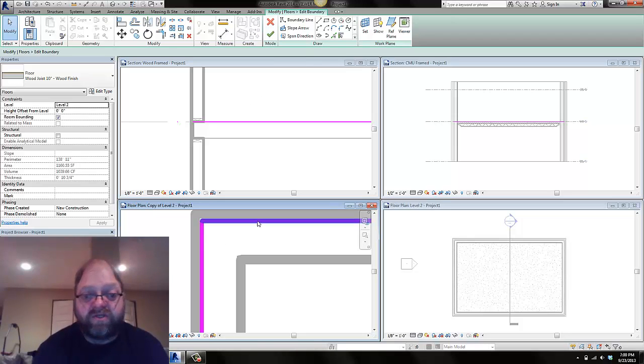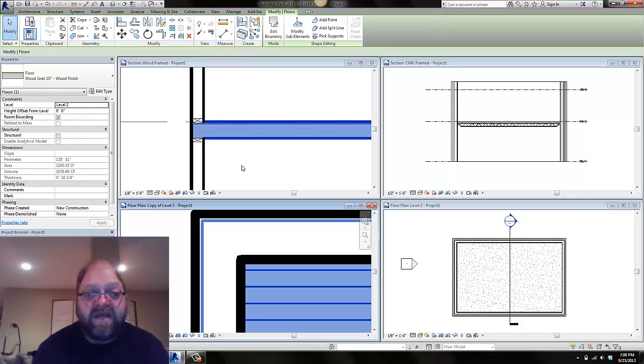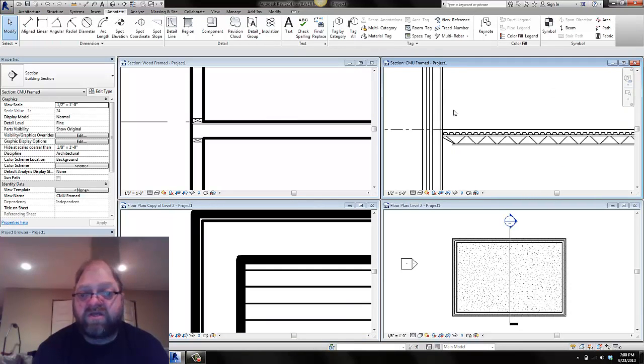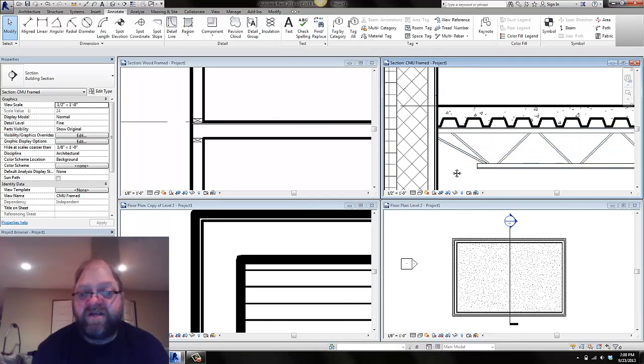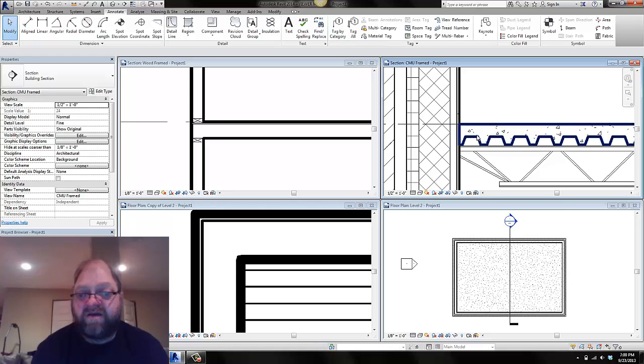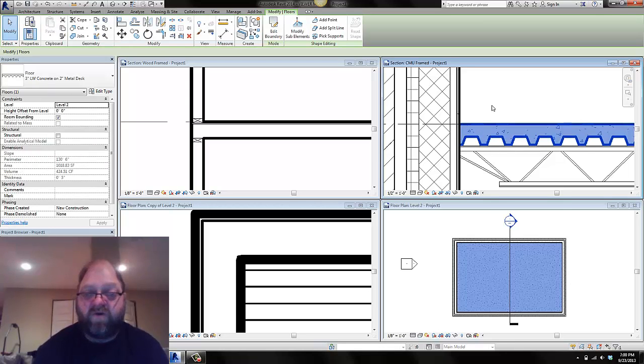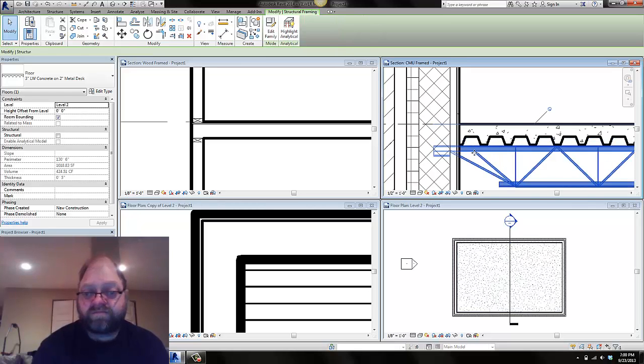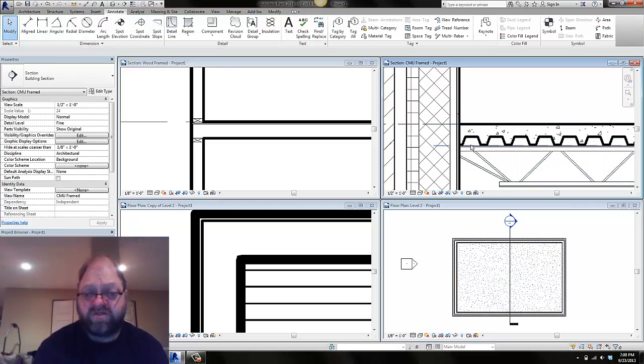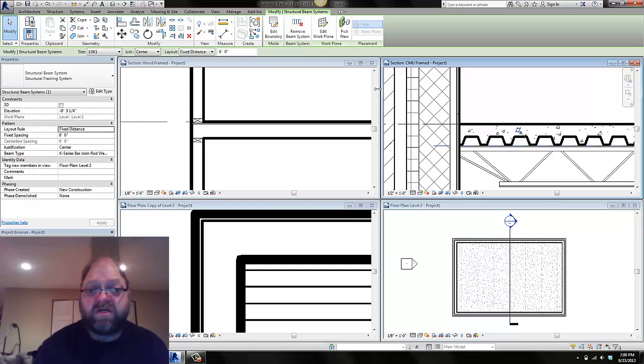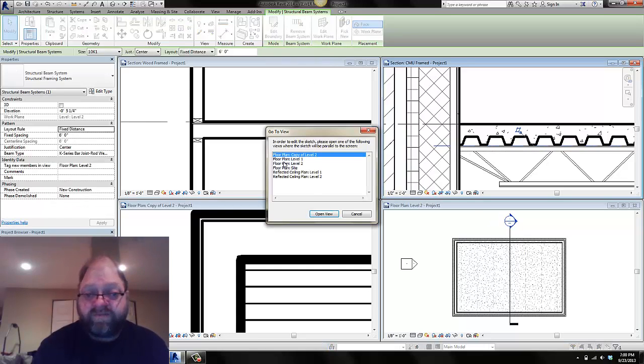And so the tool that you use, the boundary, has to be drawn in the right spot or your model won't look right. And as a contrast to that, if we look at this model over here, it's done a little bit differently. The floor is done as one element. The set of bar joists or beams here are done as a beam system.